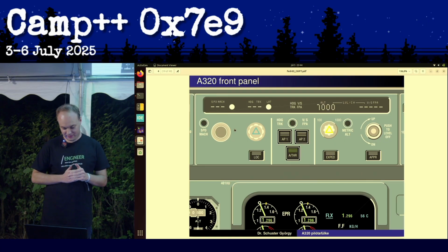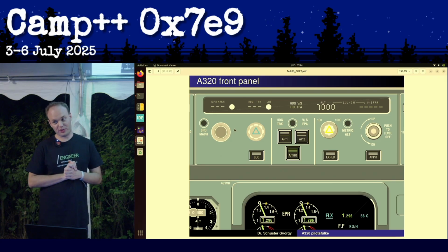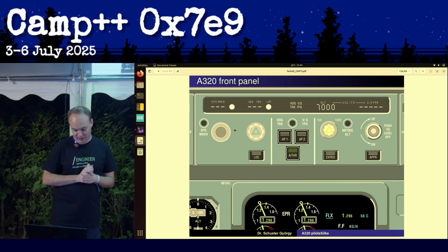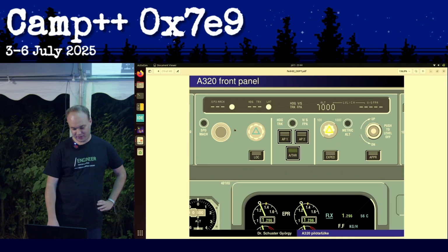And yeah, the autopilot controls the flight surfaces. Are the two autopilot systems there because of redundancy for safety, or are they different? Also for redundancy, but for example, when you are performing an ILS auto landing, I believe you have to turn both of them on because there are more inputs to handle, and they need to work together.